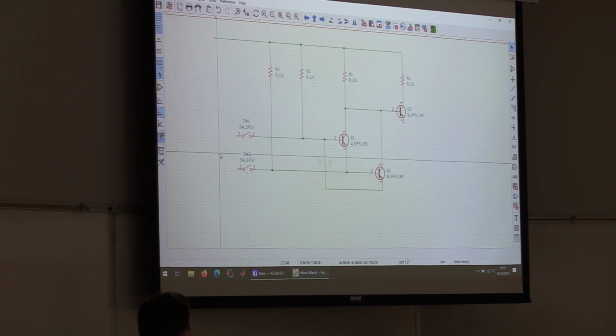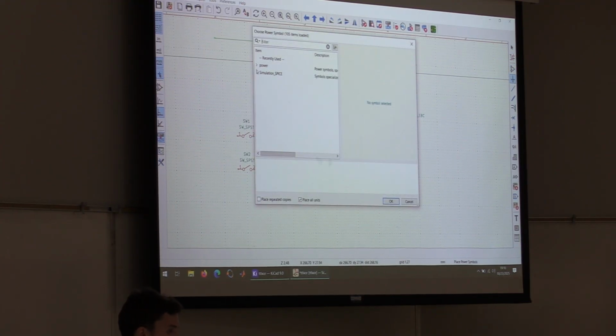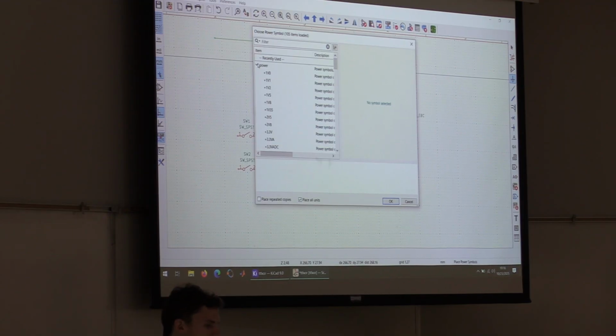But otherwise, let's go into, I guess we should add the battery. That would be a good thing, a power source. Symbols for components and power are separated by 2 menus. The ground symbol here, just below the symbol menu up here where you use to find your symbols, allows you to access all of your power related connections.